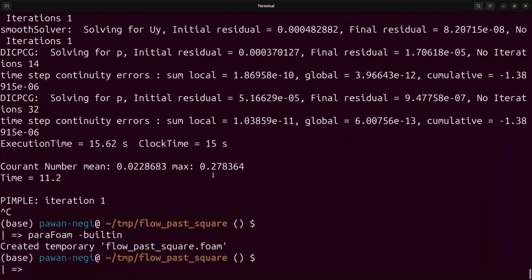With this, we have seen that there are various ways in which we can move the mesh points. OpenFOAM is coded in such a way that it accommodates for it and properly interpolates. We also should always look for the accuracy, whether the expected accuracy is achieved or not. We should not blindly do the mesh motion and expect a very accurate result.